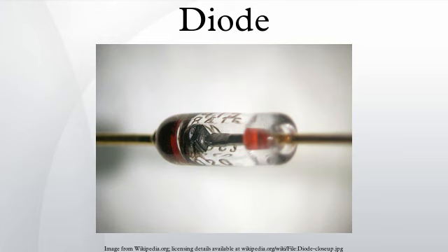Applications: radio demodulation. The first use for the diode was the demodulation of amplitude-modulated radio broadcasts. The history of this discovery is treated in depth in the radio article. In summary, an AM signal consists of alternating positive and negative peaks of a radio carrier wave, whose amplitude or envelope is proportional to the original audio signal. The diode rectifies the AM radio frequency signal, leaving only the positive peaks of the carrier wave. The audio is then extracted from the rectified carrier wave using a simple filter and fed into an audio amplifier or transducer, which generates sound waves.